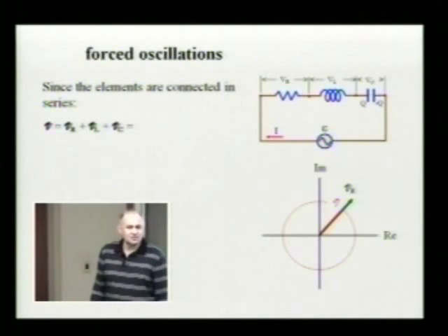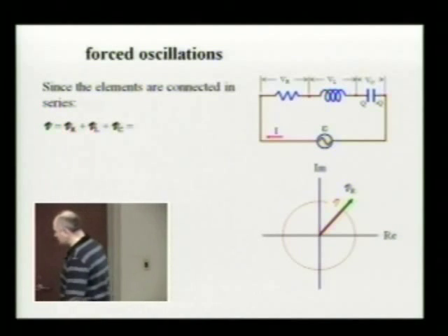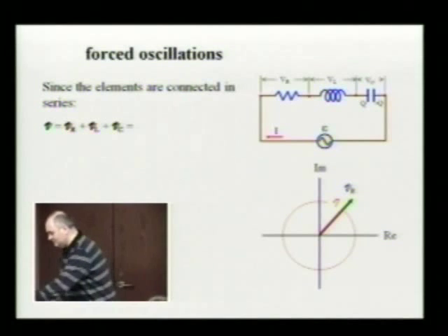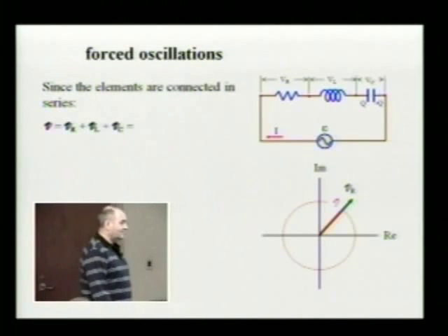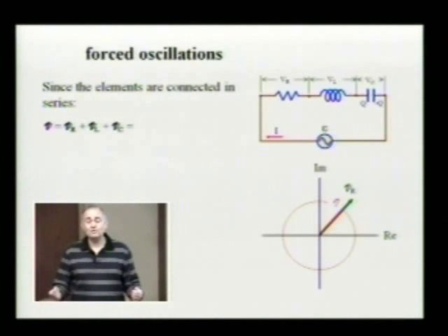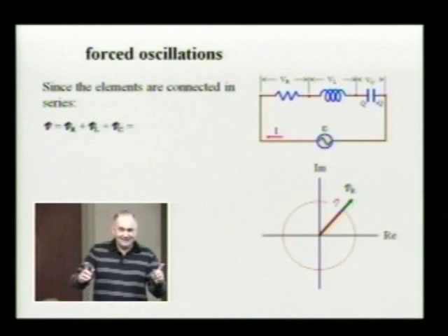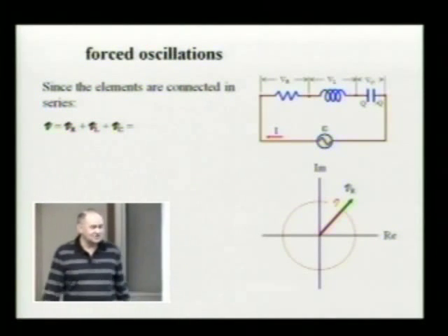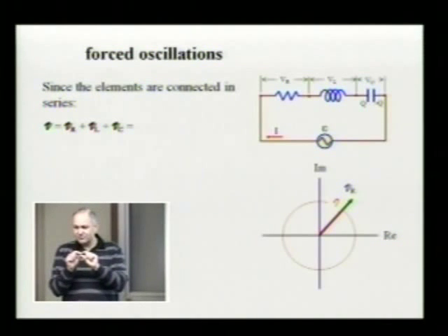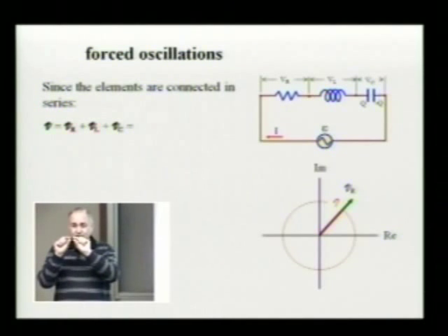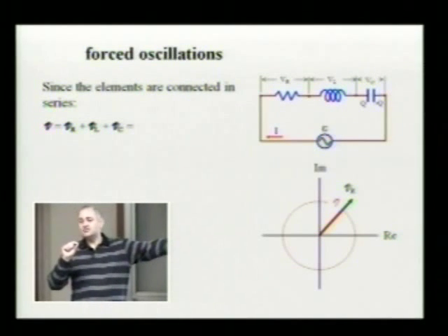He said that, well, since potential differences are measured between points, if you take an inductor, voltage travels along a straight line. And in an inductor, because it is made from a coil, current has to go through all the loops. So it has a longer way, therefore it is later than the voltage. This is just a silly story which allows you to remember what leads what. In a capacitor it's the other way. So if you remember how it is in the inductor, then you will remember how it is in the capacitor.